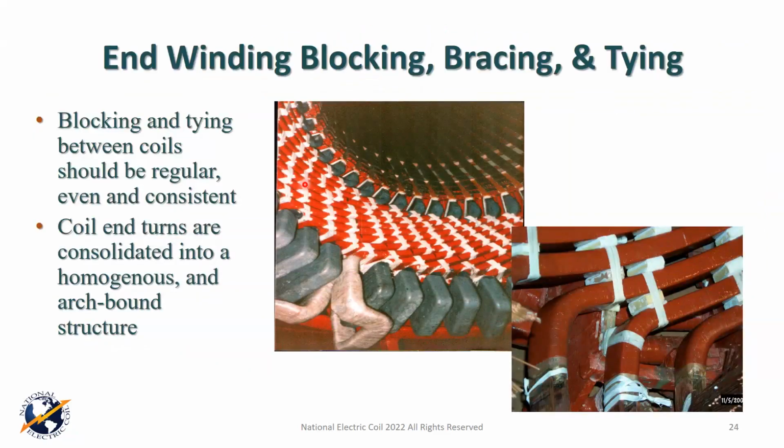All right, we're going to move to the end windings a little bit. And inside here, we've got the core of the generator, and we've got the finger plate here, and then we've got the end windings. We've got series connections, and a phase connection. And at each phase connection here, we've got a main and a neutral. There are some unusual machines. If any of you have, my favorite is a 324, because it's got six phase connections at each point around the machine. So it actually has 3 mains and 3 neutrals in that circuit at each phase connection. It's really an unusual machine.